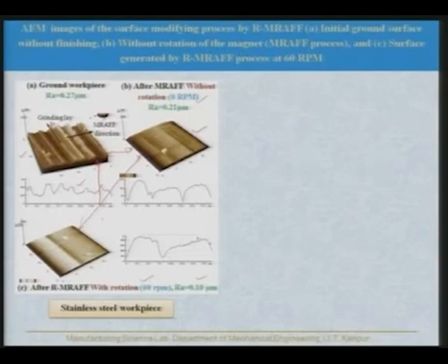First, we had the grinding marks very close to each other, but much wider than on the ground surface. So, this has improved, but in this case it has further improved. Some of the grinding marks have disappeared and the finish is better, it has come down to 0.1 from 0.21.